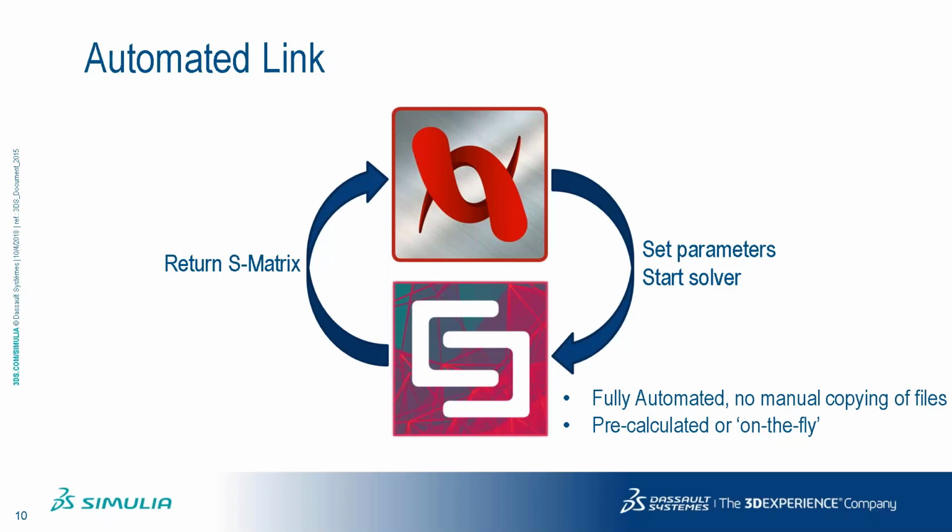So in that case, you can pre-calculate a number of combinations, access them later on, and even interpolate between results. This is a potential workflow where you pre-calculate a set, and then you do automatic interpolation until you reach a point where you feel, okay, I do need another data point, and then you can just recalculate that on the fly.